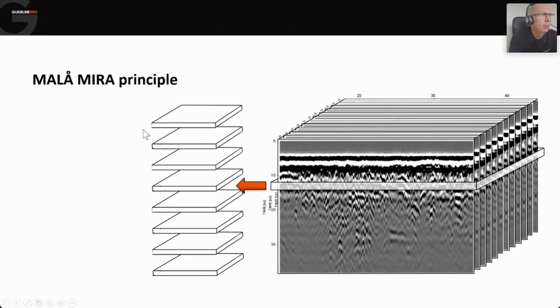They quite typically refer to them as the time slice, because we're looking down through time. When we convert that to depth, we're looking down through depth, obviously, and in effect we can start to peel the ground away and start to look deeper and deeper down into the soil. And this is now giving us our Y measurement across the axis. Before we had our Z value, across this edge we had the X, and now we've got our Y measurement, and that is our 3D measurement.